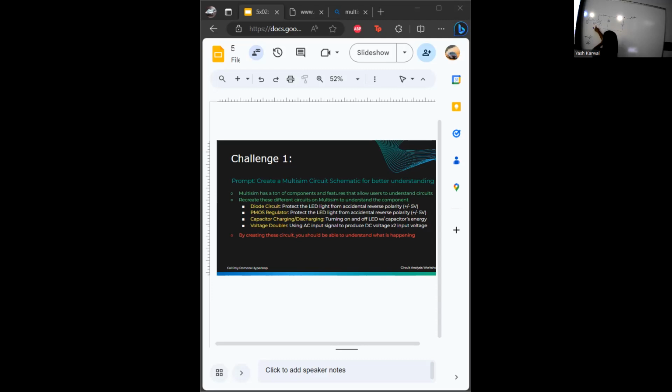So when 5 volts is going in, remember the current flows from positive to negative, right? So let's go on an adventure. It can also go this way too? No, it cannot. Just this way, right? It hits this diode, 0.7. It depends. It's not always 0.7. Depending on your diode, it could be different.